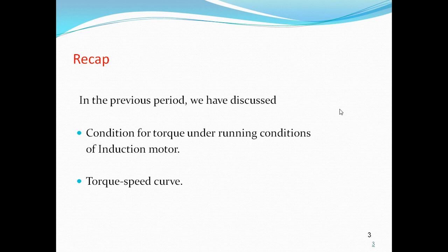How did we derive it? We took the full load torque equation and differentiated it with respect to the variable, that is slip s, and equated it to 0. Then we got a condition.